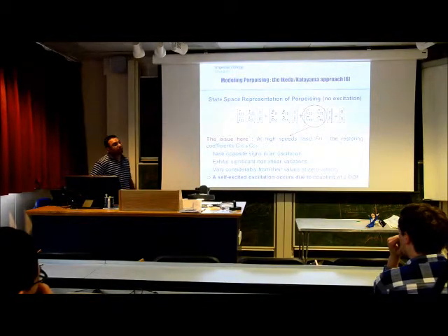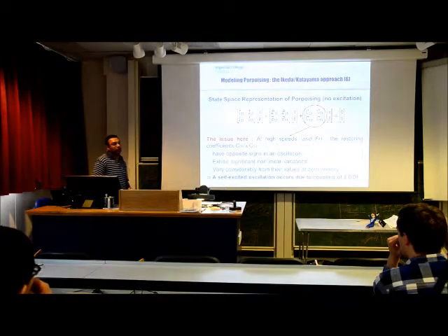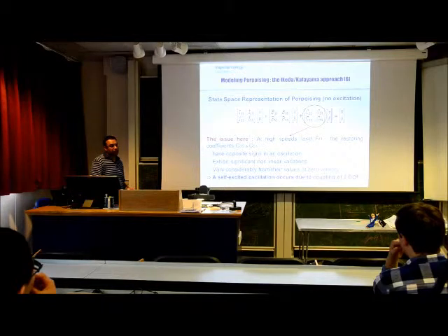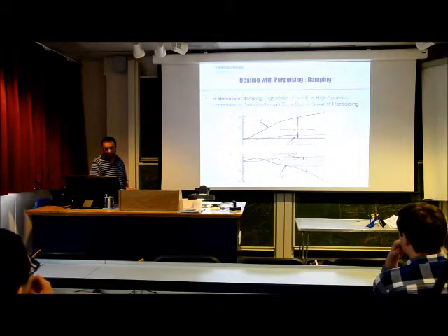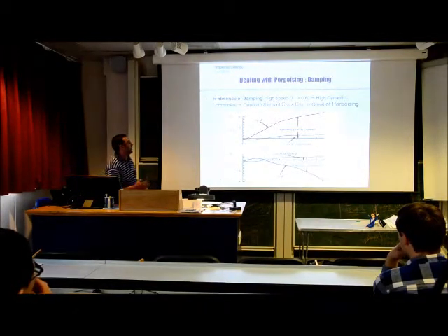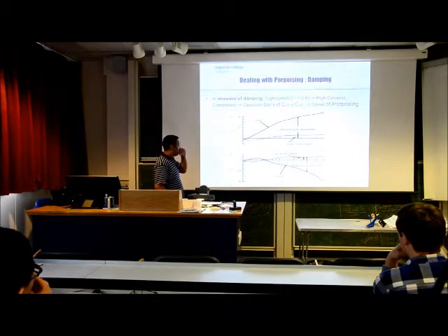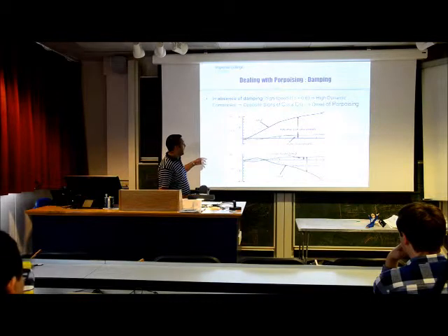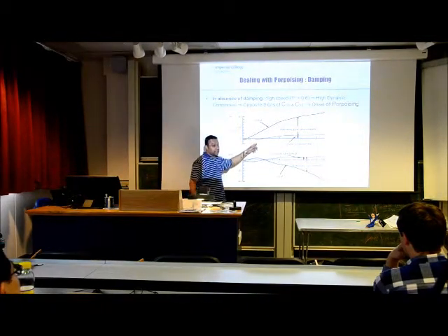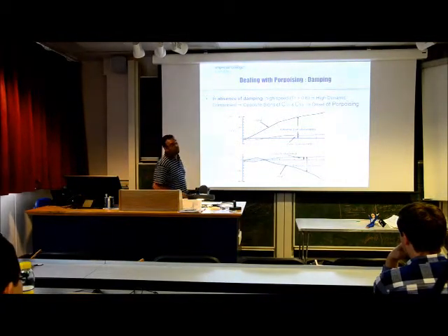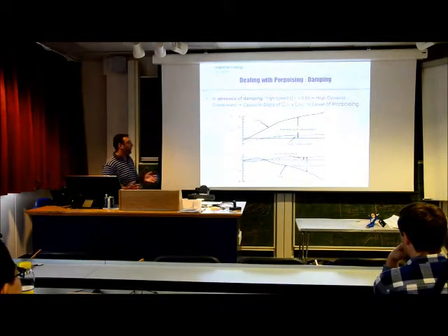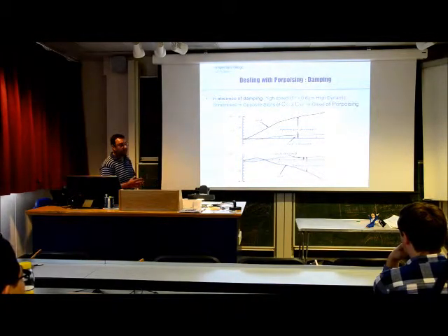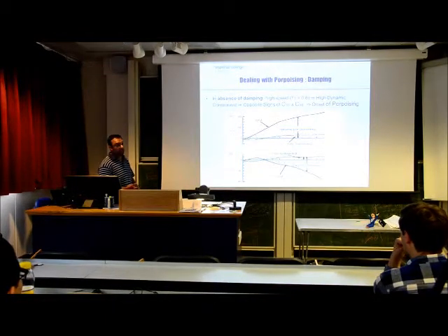It's difficult to conclude about the porpoising stability beyond a certain speed, because you have a lot of non-linear effects taking place with two of the inertia coefficients. And beyond, for example, here at 0.6, we cannot linearize. I mean, you can linearize if you want to, but that would be a very false representation of what goes on in reality.